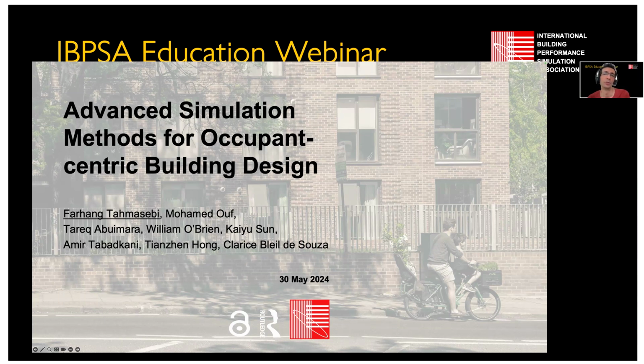Yeah, so the two tests that I showed here are both done in EnergyPlus. And I wouldn't say there is any inherent advantage in using EnergyPlus over others, but there are things that you might need to be mindful of. One is the possibility of coupling the tool with external interfaces, because you have this runtime data exchange that you need to manage. By runtime data exchange, I mean that your building simulation gives you, at a specific time step, let's say, an indoor temperature.